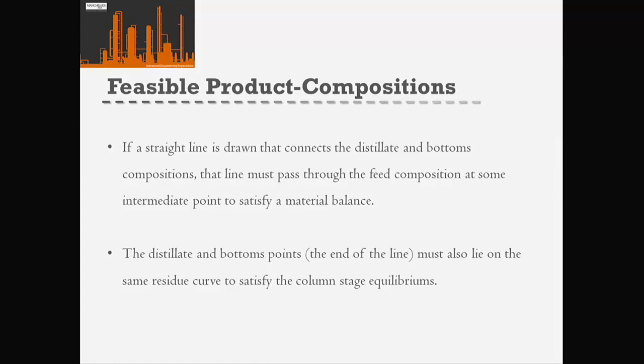As I mentioned, and exactly the same as when we looked at liquid-liquid extraction, because we've got a sequence that is essentially a mass balance, we can represent that with a straight line. Because our mass balance points are essentially our distillate composition and our bottom product composition, we can have a straight line that passes between the distillate and the bottom product.